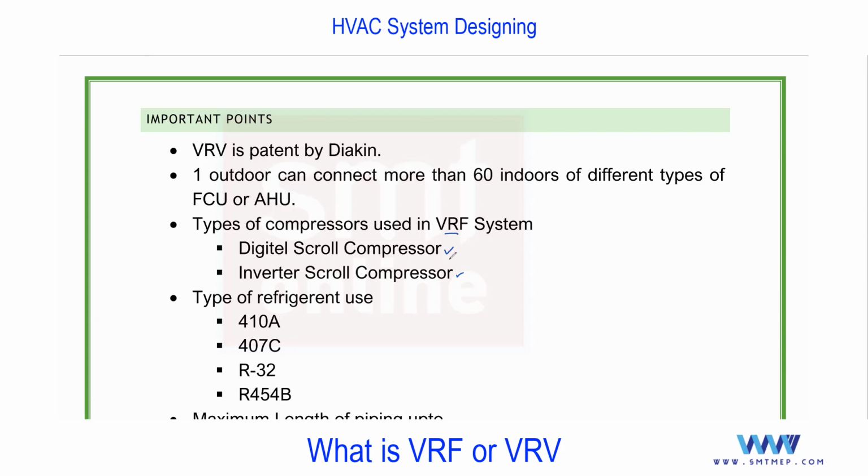And as a mechanical, you know the different types of compressor, no? Screw compressor, scroll compressor, reciprocating compressor, etc. But remember, in VRF we are using the scroll type. And even in split systems with the inverter type, you'll find scroll. And now many vendors, even in split, are using the scroll because from the noise point of view or efficiency point of view, we have advantages. So as a mechanical, I believe you know what a scroll compressor is, right?